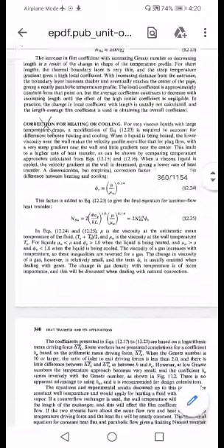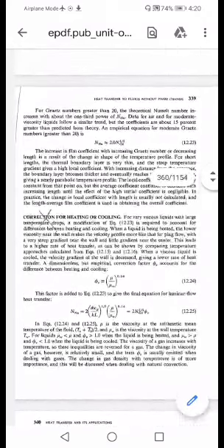So up till now we have been discussing the various dimensionless numbers like the Nusselt number, and now the correction factor for heating or cooling is very essential. Generally, when a hot or cold fluid which is very viscous is flowing through any pipeline, the viscosity changes with temperature. So we need to add the correction factor, which is phi e equal to mu upon mu w raised to 0.14. Now this factor is added to the final equation for laminar flow heat transfer.